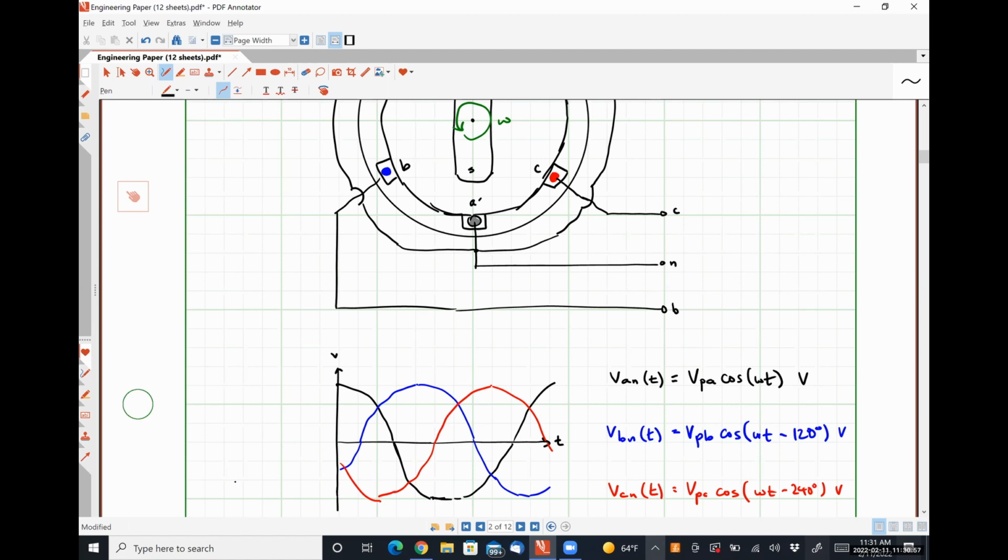So this is how our three-phase voltages are generated. We've talked about positive phase sequence, which effectively just means omega is counterclockwise and we get negative phase angles. For a negative phase sequence, omega is clockwise and we get positive phase angles. In this class, we're always just going to deal with a positive phase sequence. It really literally means nothing except that the motor or the generator is spinning in the opposite direction. So it makes no changes whatsoever on our analysis, except that all of our phase angles will become positive instead of negative and vice versa. All right.